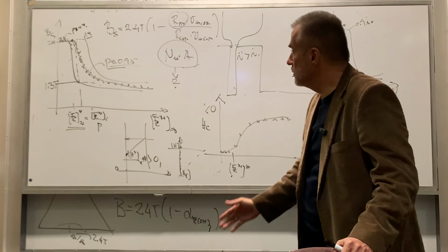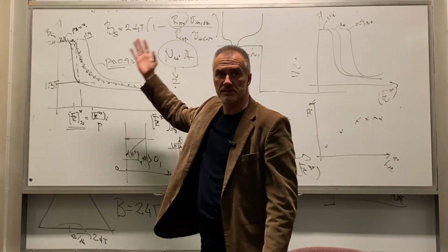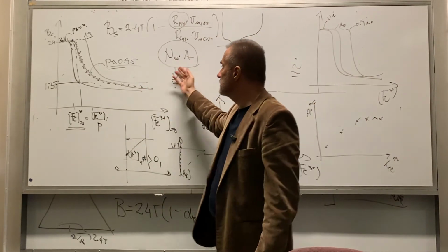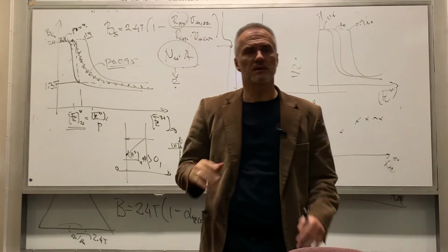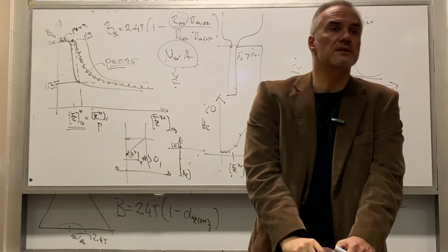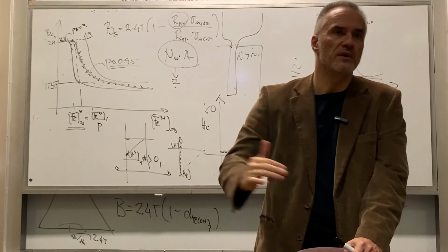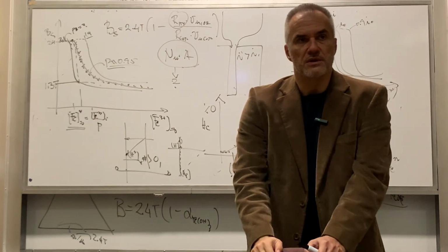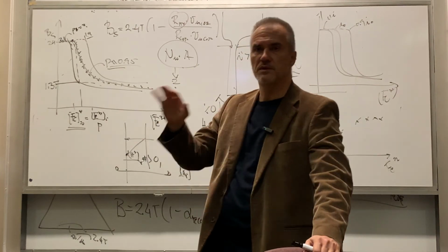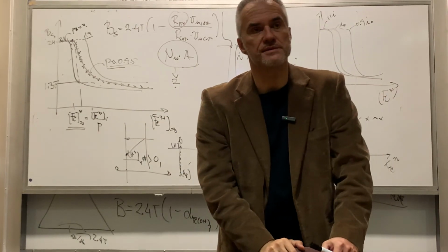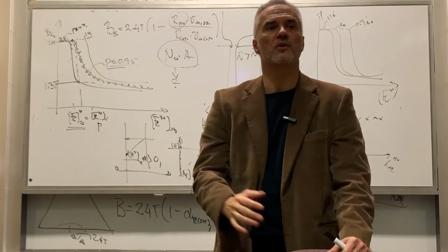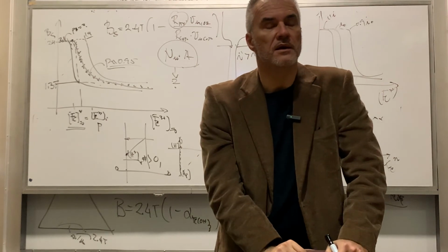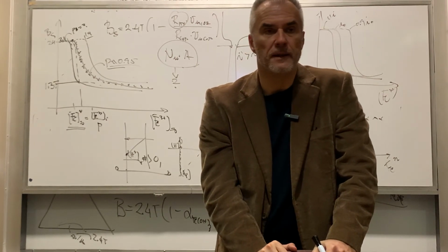And P is close to 1, almost. You can almost say it's 1. It's not going to affect you much in terms of understanding. And the only thing that you come out with is this constant, right? Everything else, more or less, is fine in literature. And the material I sent you gives you an even more elaborate and deep discussion of the shape factor and stuff, which I avoid because we assume hemispherical nuclei, 45 degrees wetting angle. The stuff that I have in papers is a little bit more elaborate in that it could be any shape and whatever, but you will understand what I'm talking about.